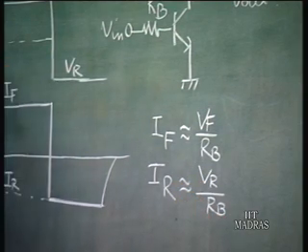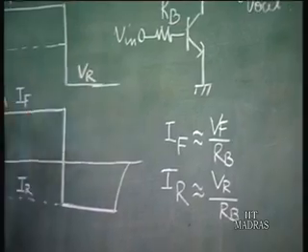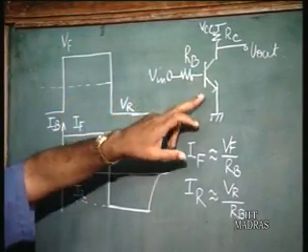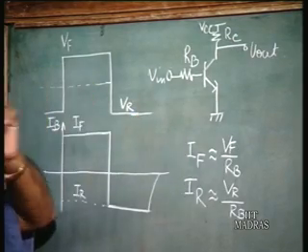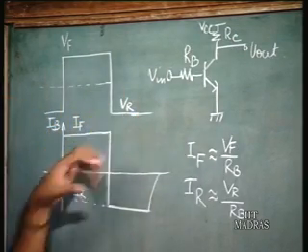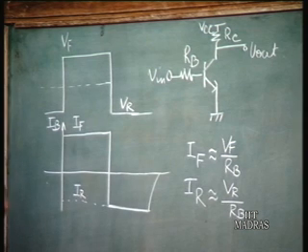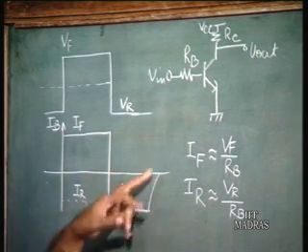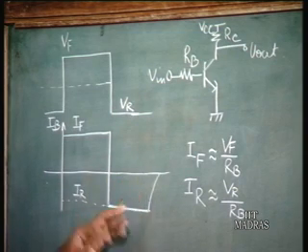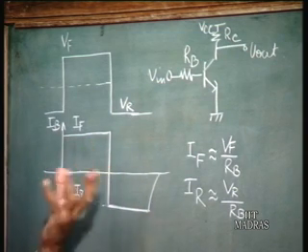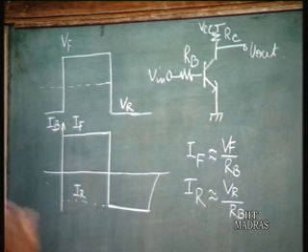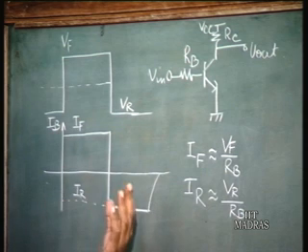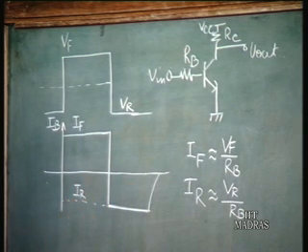That is because we assume here again that the input voltages, that is Vf and Vr, their magnitudes are much greater than the base emitter voltages, because the base emitter voltage in this period is going to be very small compared to these input voltages. Only at this point in time, when the base charge has been completely discharged, the base emitter voltage tends to become sufficiently negative, and so the reverse base current falls.